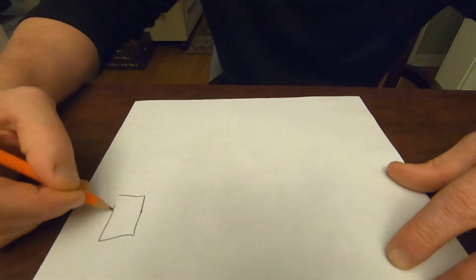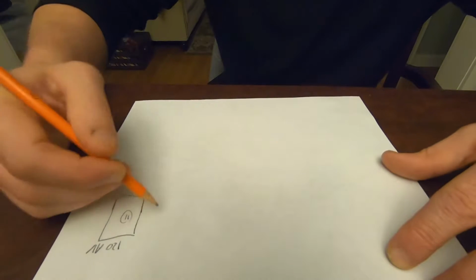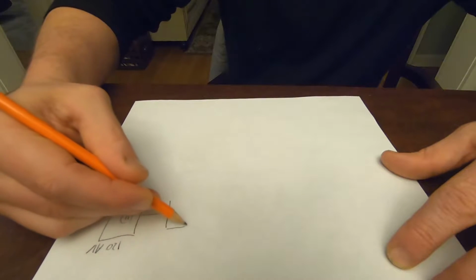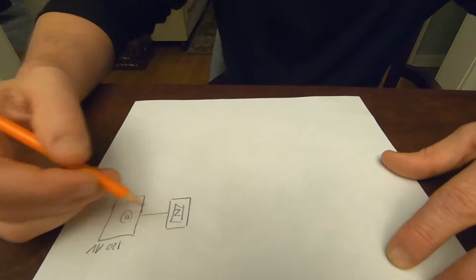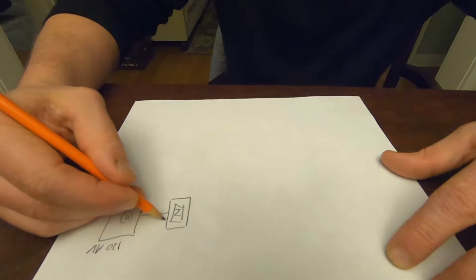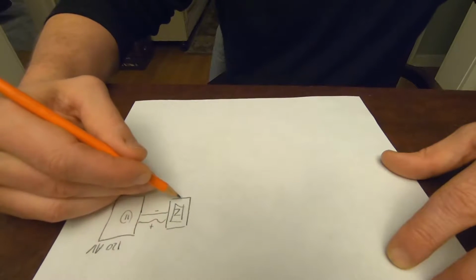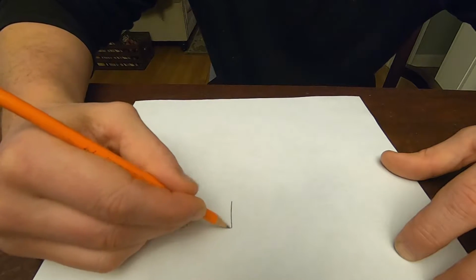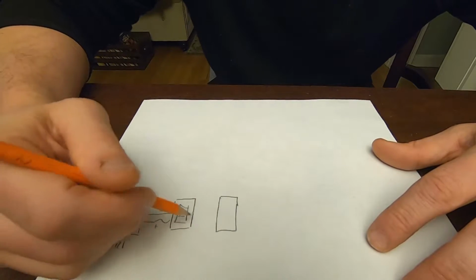So here's the new plan. We've got a wall outlet with our 120 AC. From there, we're going to have a single gang electrical box with a Z-wave dimmer in it. Here you're going to get your positive and your negative feeding the Z-wave dimmer. Then we're going to have another single gang, strategically where the other transformer is. They have to be separate. I don't want to use a two gang.